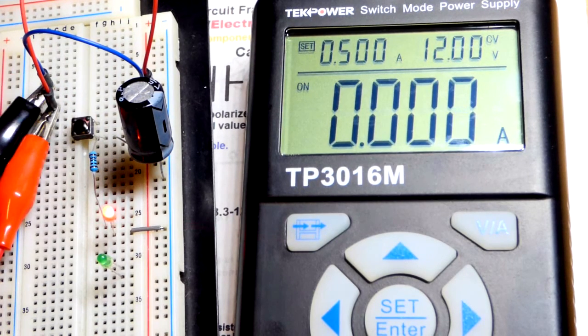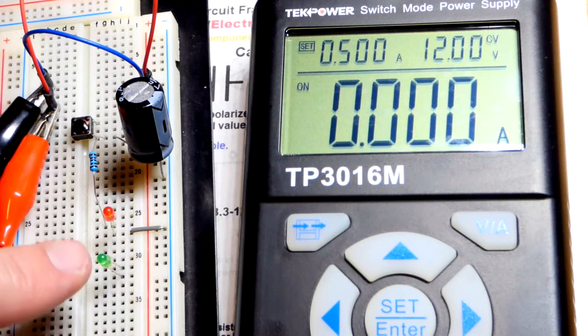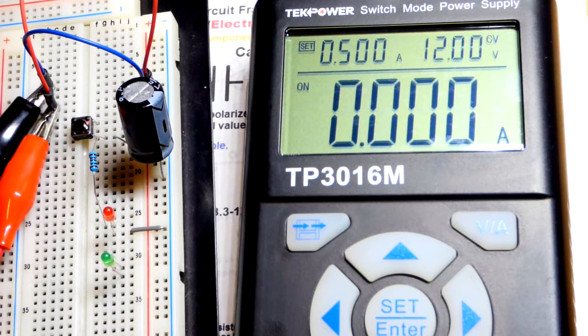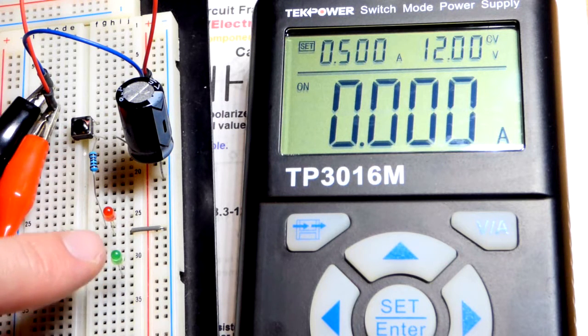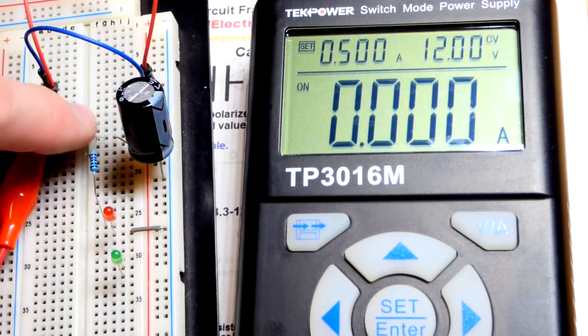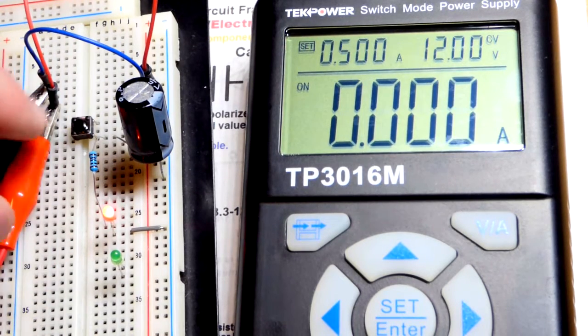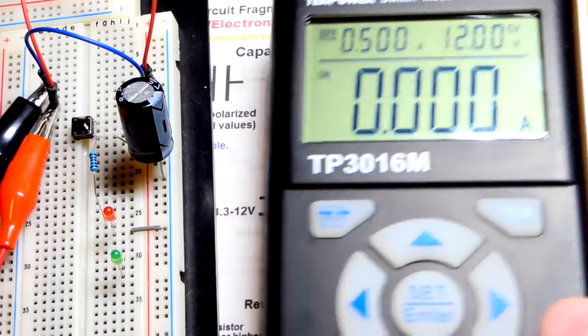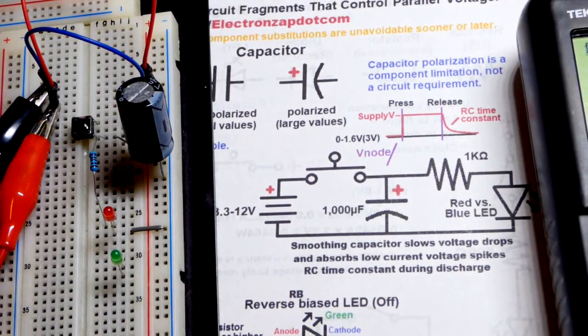So that's the thing. At the lower voltages, you may need a green or blue LED for a particular setup for brightness. Even though it's using less current, there may be so little voltage that you need a really bright, obnoxious LED. Whereas with like 12 volts, this red LED is just fine. It's probably going to be bright enough, even with a 1 kilo ohm resistor right there. So that was a couple of adjustments.